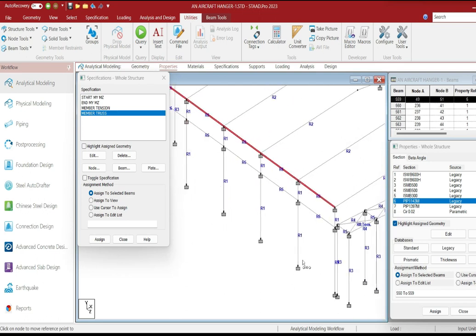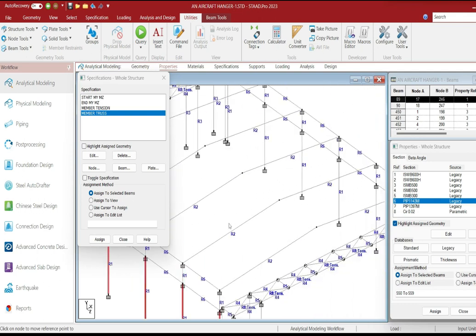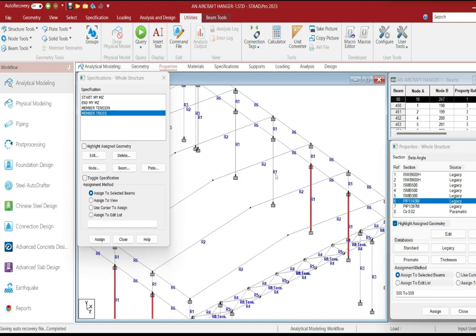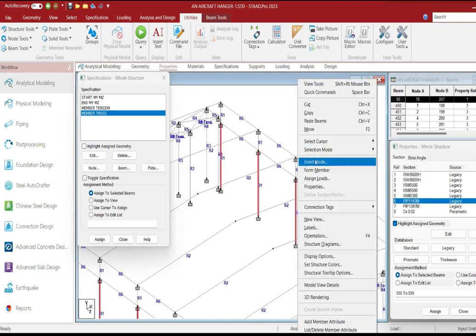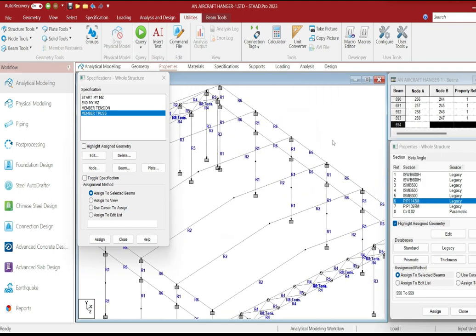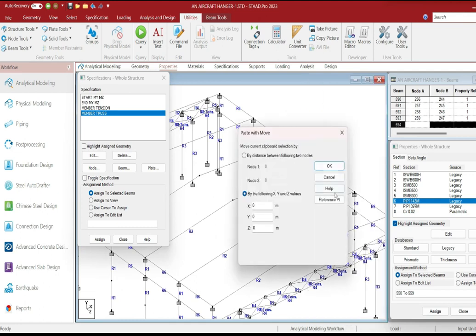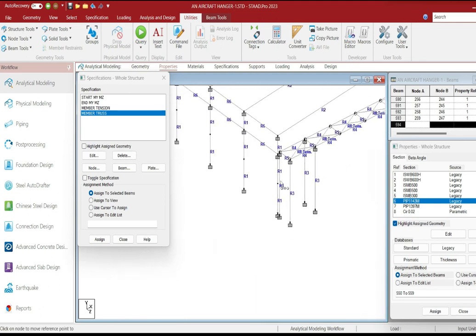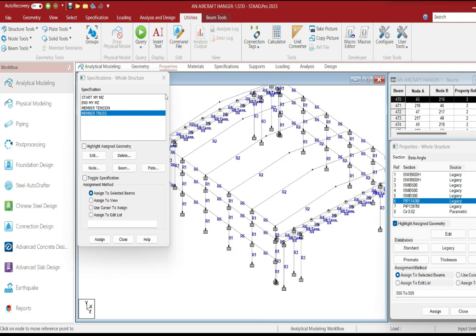Now at the center point also we need to have some struts. So we select all these beams, then all these columns, then insert node, add midpoint. Okay, midpoint is added. Then we already had this place strut selected. So paste, take the same reference, same thing, and paste it here. So our strut has been added.